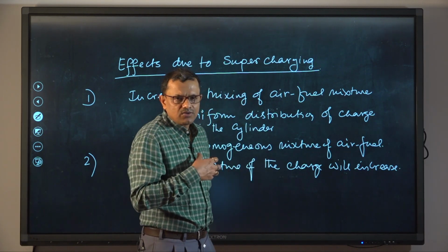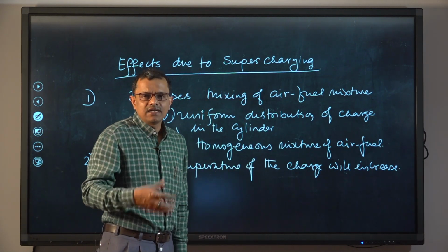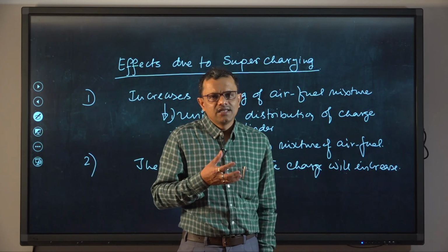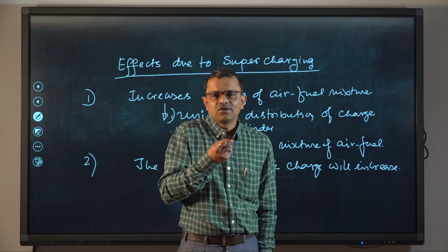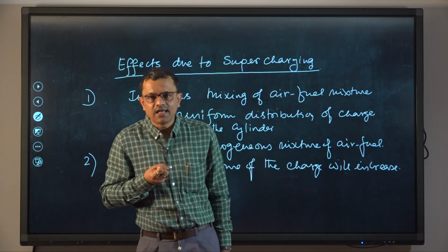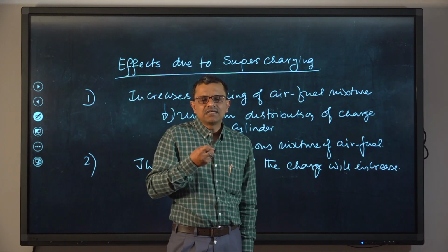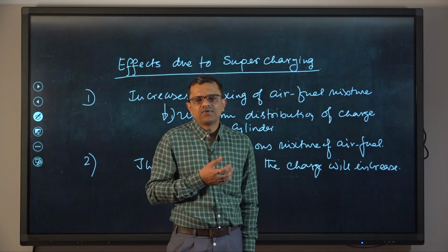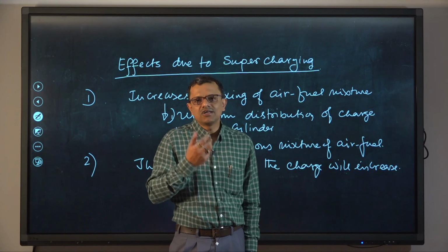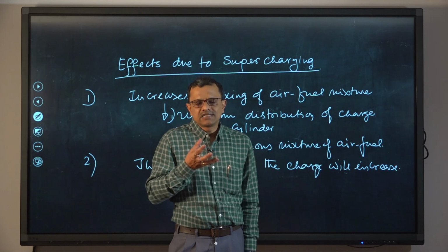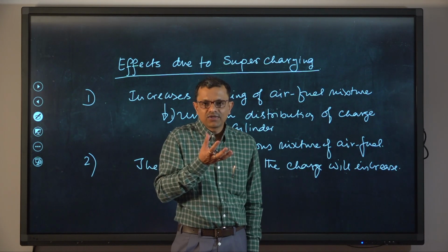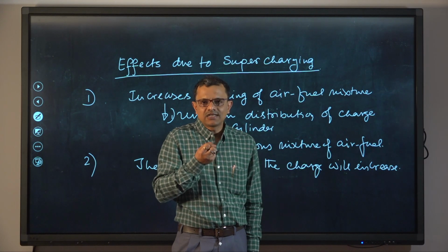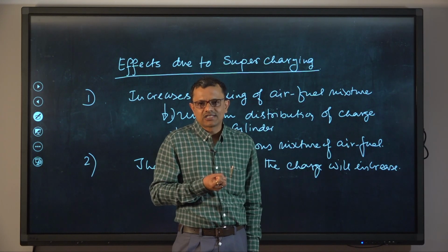Now, what would be the detrimental effect? With increasing temperature, the incoming charge temperature will be higher, and that may make it vulnerable to the initiation of detonation when the charge is compressed further, because the charge is drawn into the engine cylinder during the intake stroke.